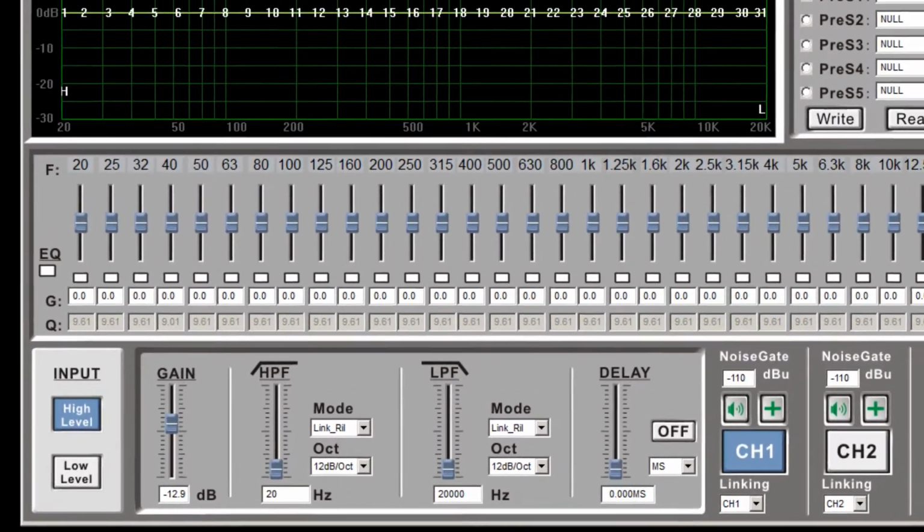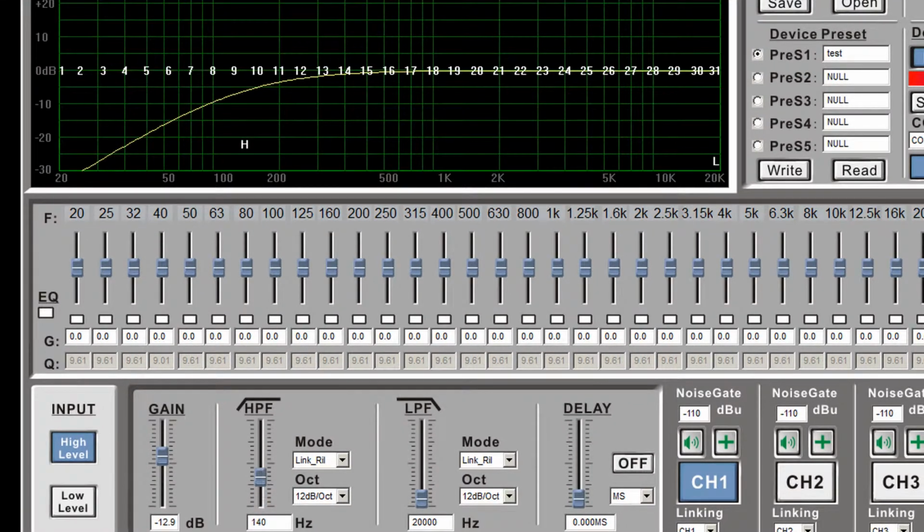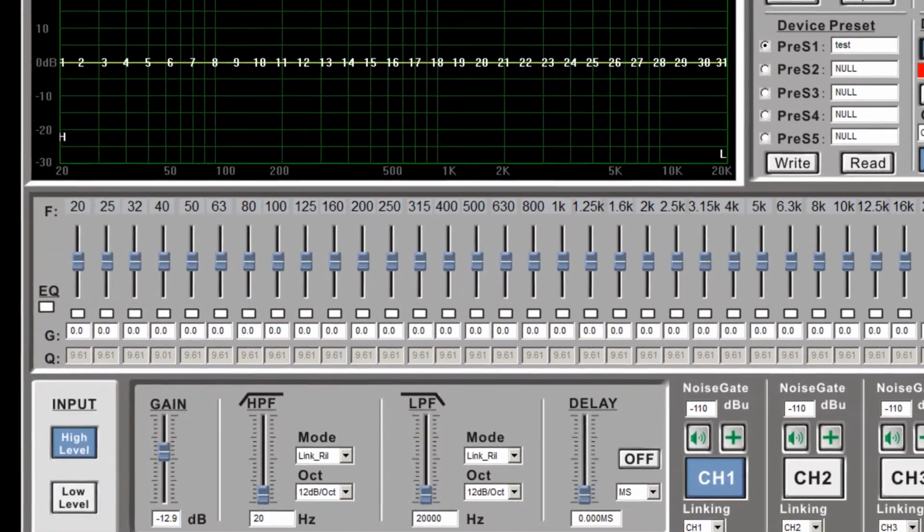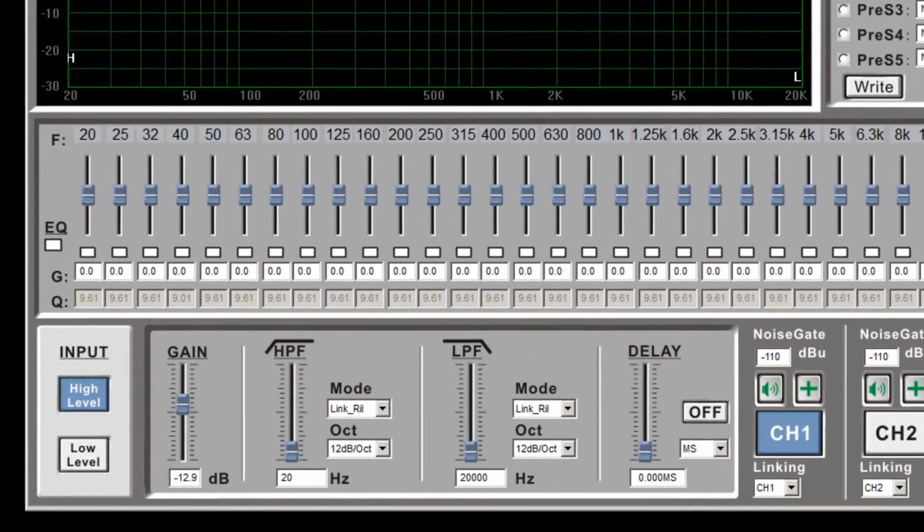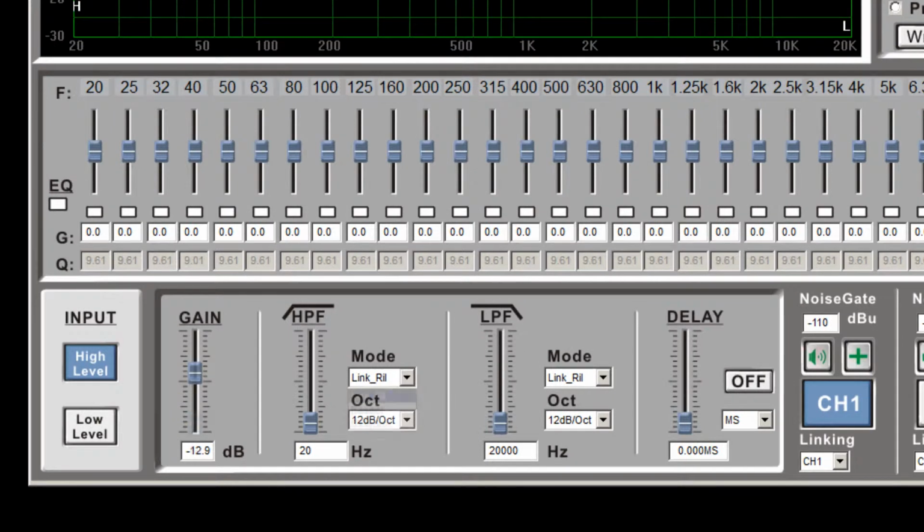In the lower section there is a crossover control, two filters, high and low frequencies, which are set up separately. We can select the type for each filter, Linkwitz-Riley, Bessel or Butterworth, and the steepness of the decay characteristic, that is the filter order, and of course the cutoff frequency. The last is set in the range from 20 Hz to 20 kHz with an accuracy of 1 Hz. Out of spite, I tried to enter a fractional number, but it didn't work.